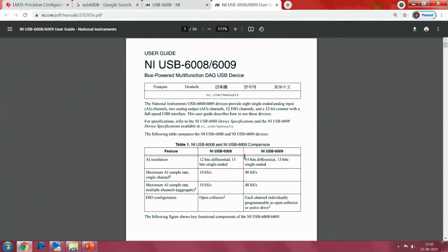So here it shows that it has a 12-bit ADC. In yesterday's class we discussed an 8-bit ADC. If we are using an NI myDAQ, it probably has an 8-bit ADC, or if you are using any data acquisition device with an 8-bit ADC, whatever we discussed yesterday will work out. Of course, the generalized concept of interfacing and the selection of the ADC are pretty much the same, provided the formulas or the resolution of the ADC are slightly changed. Based upon the reference that you selected, the number of levels the ADC will have depends upon the resolution of your ADC.